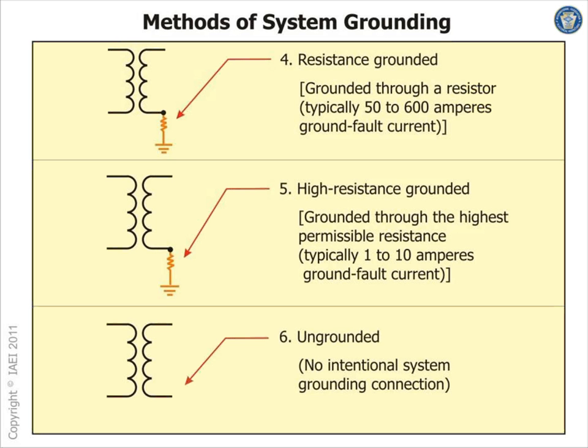But when you put the impedance right here, you basically eliminate the hazard associated with tripping your circuit breaker because of a ground fault. You can monitor any ground fault and decide if you want to act on it at any time. But I guess the major part of it is the survivability of your system. It makes your system more survivable, and at the same time eliminates the transient coming out of ground faults in your building.